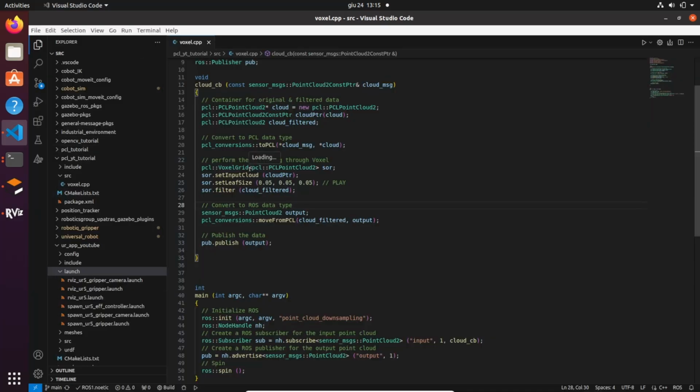So the point here is that we now know how to voxelize your environments, and the key factor that you need to play with is this one, because remember, it's going to be a trade-off. The higher this leaf size is, the fewer points you're going to have, so the process will be faster, but the drawback is that you risk not sensing the environment properly: you don't know where the table is, you cannot distinguish it from the object of interest.